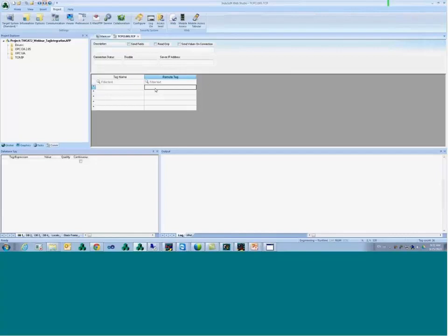So you could have just one web studio station talking to the PLC with the driver and exporting the tags using the TCP/IP task. The communication is going to be pretty fast as well, because this is the same task that we use on the viewer module. Whenever a tag changes on the viewer, we send it to the server project, and from the server it goes to the PLC. So that would be as fast as the viewer.